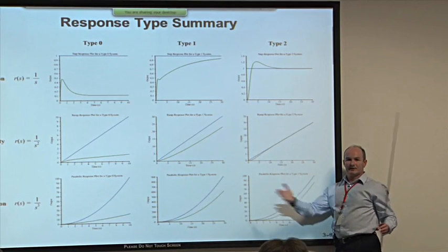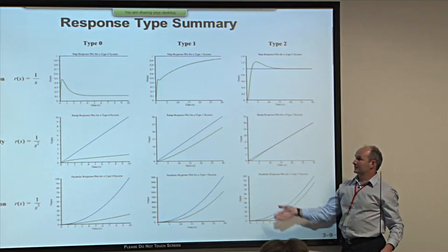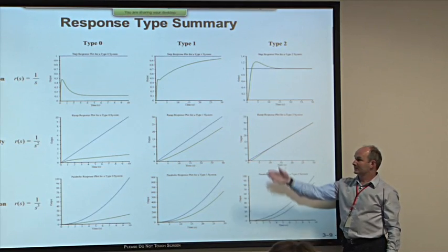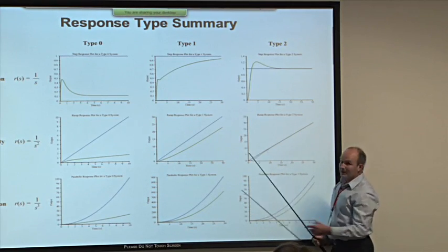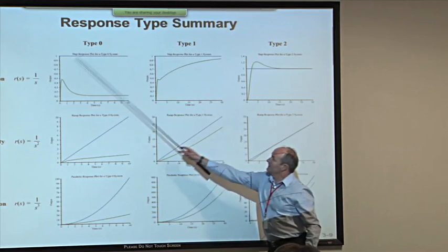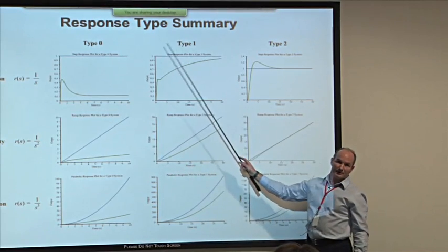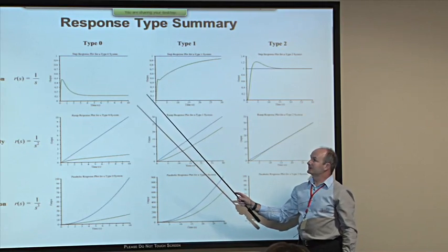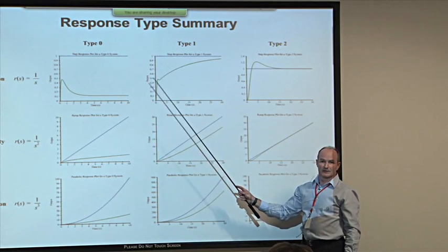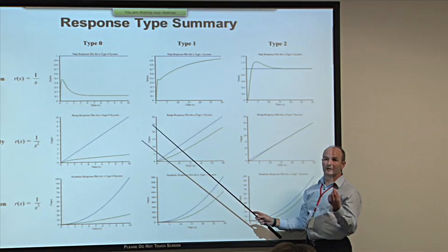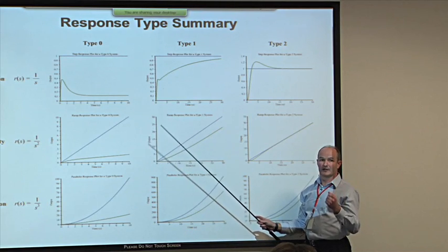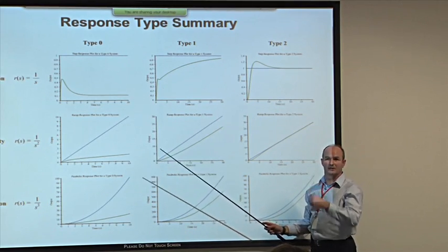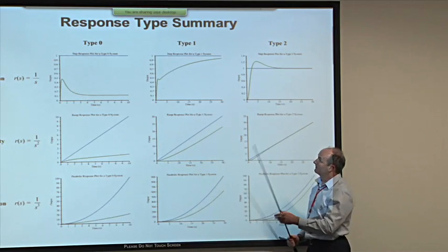Now, I apply this theory rather generally for all types of system with lots of integrators and different types of stimulus. But for our purposes, most often, it's these two cases which are important. Most often we're applying step inputs, and most often we want zero steady state error, which obliges us to have one integrator inside the loop. Doesn't matter where it is. It can be in the plant or it can be in the controller, but there's got to be one of them somewhere.